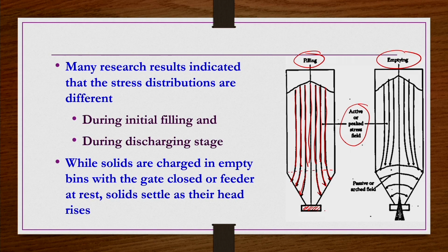Now, when you open this bottom opening, so you are collecting the material like this. Then what happens? At least in this portion, that is in the conical section, not in the cylindrical section, whatever the material is there is moving laterally, and the material is contracting in the lateral direction. So, the stress is also moving in a lateral direction. These stress fields are known as the passive or arched field.